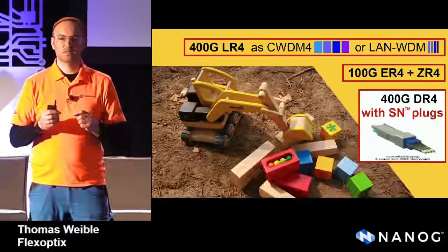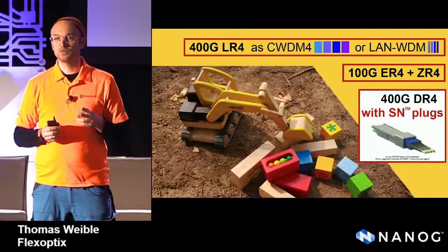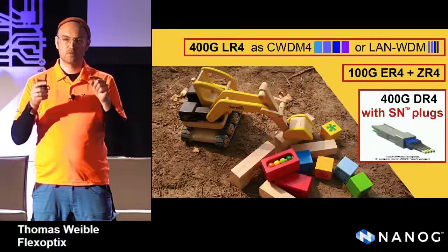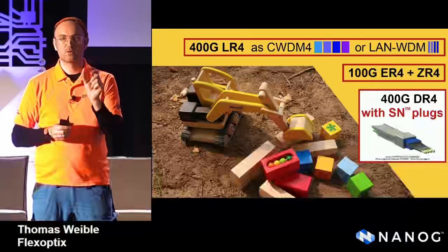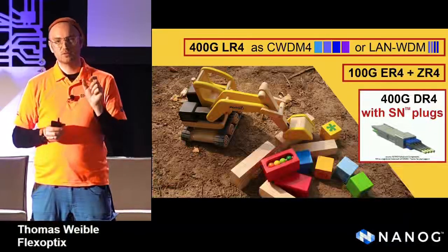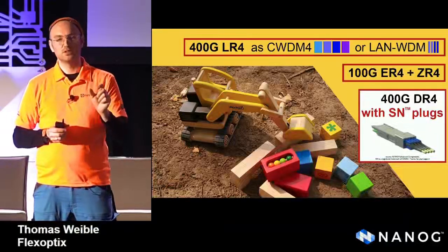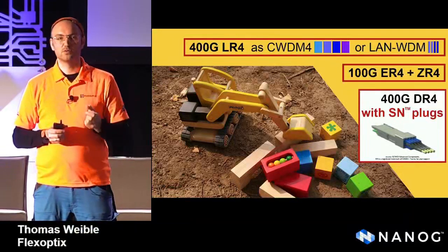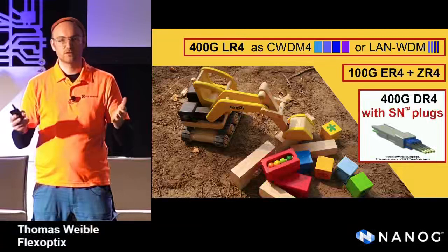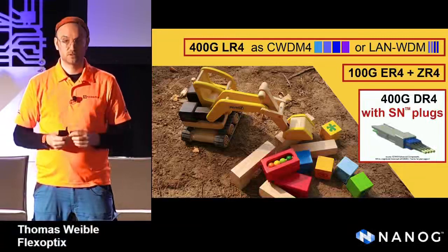The SN plug itself is a single plug holding 2 ferrules. In combination with its counterparts, it's going to be a cluster, a block of 4 plugs combined into the receptacle of a QSFP DR4. And if you want to maintain a single link, you can just release two ferrules, and the other 6 ferrules will stay in the transceiver.